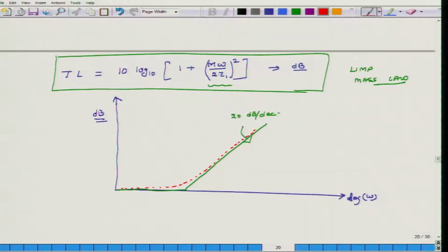Okay. But in reality, walls are not perfectly rigid. So, at very low frequencies they behave as rigid masses, but as you increase the frequency they have their own resonances. So, as I move on this positive slope line, at resonance points, initially the actual curve may be like this, but these may be related to resonances. So, at resonance the transmission loss becomes higher, and then it keeps on going, and then you may see actually a dip.